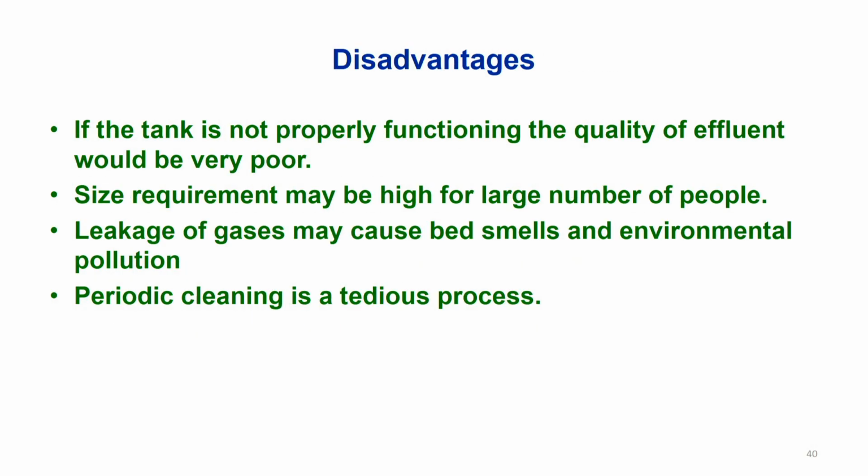What are the disadvantages? If it is not working properly, then the quality of the effluent may be poor, and it can also contaminate the adjacent environment. Size requirements sometimes may be high depending upon the number of people living in that locality. Leakage of gas may cause bad smells and environmental pollution. This is because methane is generated, so it has to be vented in a safe manner.